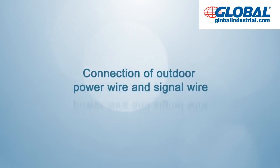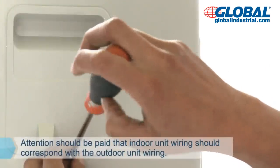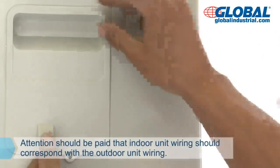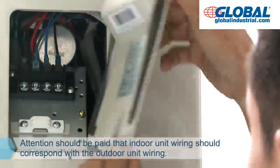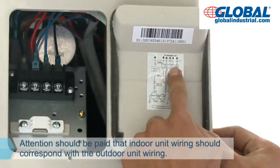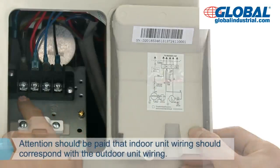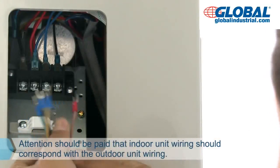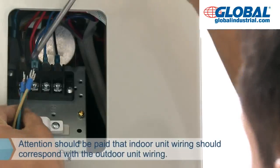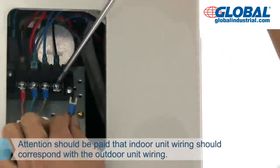Connection of outdoor power wire and signal wire. Open the large handle of the outdoor unit. Connection is conducted corresponding to identifier with reference to wiring diagram. Attention should be paid that mode of connection should correspond with indoor side. Incorrect wiring may result in damage to the electrical control board.